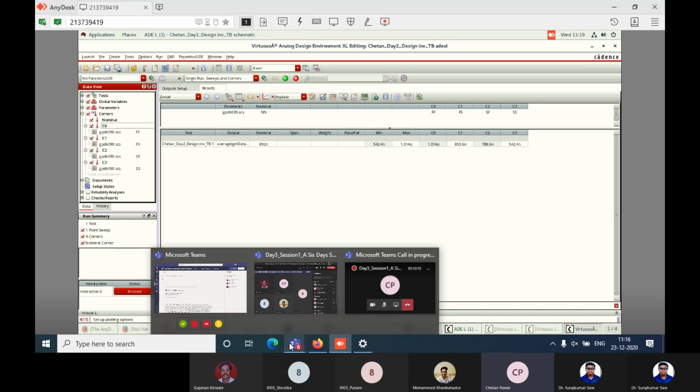Good. Now how do you calculate delay? Sir, adding the delay function from the bottom. Delay function, right? Yes, sir. Click the delay function then. Good. Now select the signals properly. One signal should be what? The net input 5 signal. Other signal should be what? The output signal, right? Yes, sir. Slash net 5 it should be.